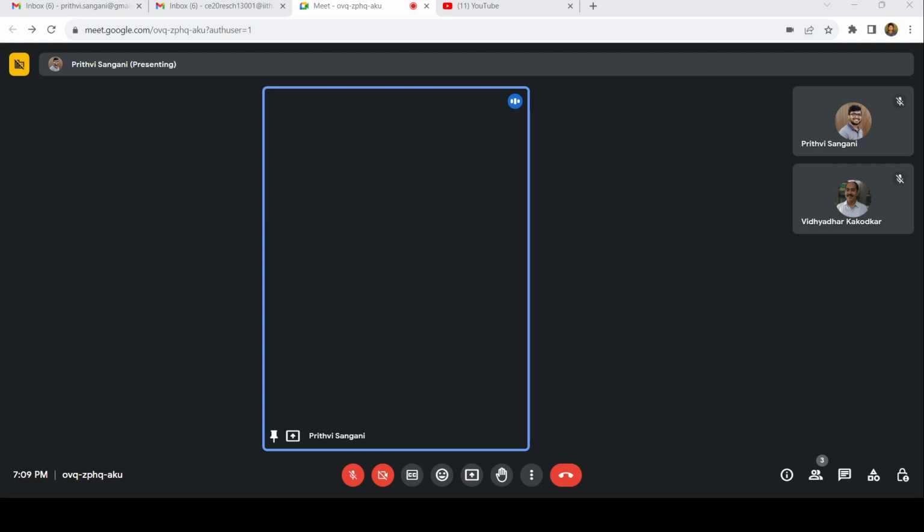So what happens for delta 1? Delta 1 can be written as sum of FiUiLi by AE. AE is constant. I did not mention AE, but AE is constant in this question. So this is about delta one. As we see here, this term is zero, this term is zero, this term is zero, right? So we have only AB and BC. Only these terms will make some significance towards our deformation formula, right?